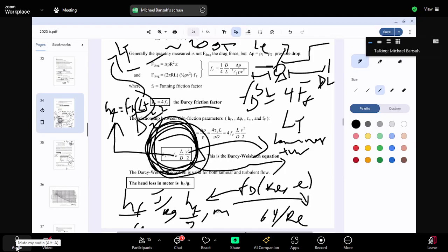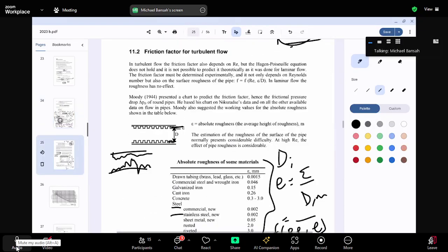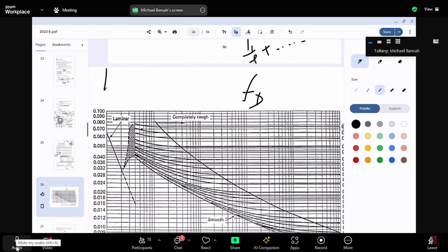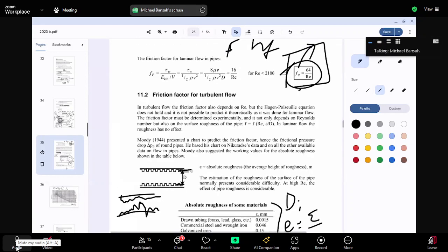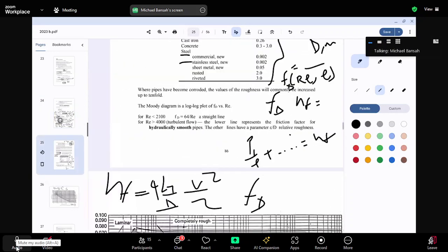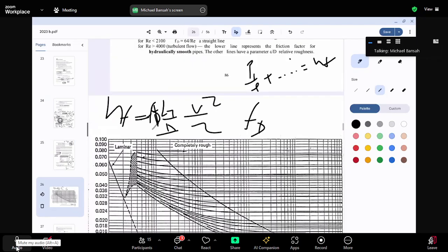When you use the total length, it means you account for all of those. What I said earlier is to get FD. When I find FD, I come and find my HF, knowing my total length, knowing my velocity, is that fine? It's FD. All right. So knowing my FD, then I can calculate my HF.